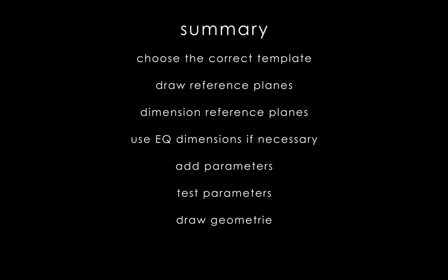Once you tested your parameters, then you just draw the geometry. You use the extrusion tool or use the sweep tool, and then you just align the geometry to your reference planes. And never forget to lock.